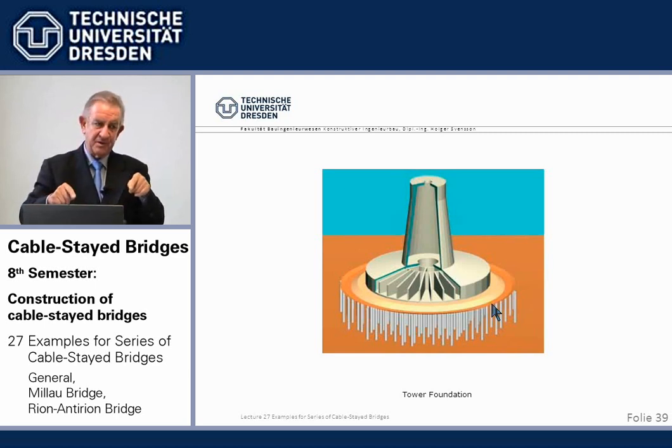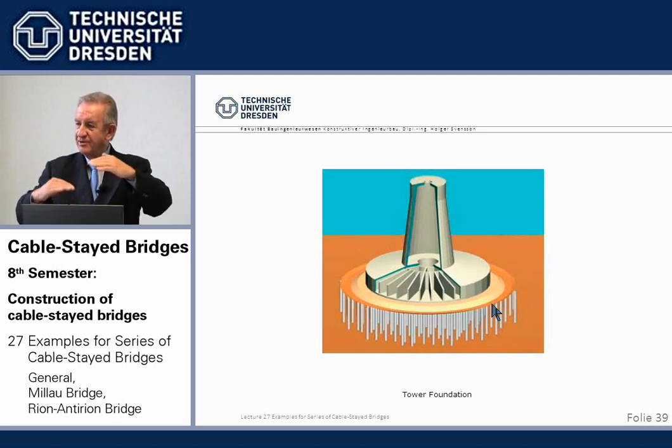It's not the first application at all. I've given you the reference, but it's the first for bridges. I think it has been done for buildings or so, but it's the first time. And it has been also used, you may recall the Golden Ears Bridge in Vancouver, BC, which I showed you. It's an extradosed bridge by Bilfinger, lately completed, where I was checking engineer. And they have also taken this because there's also the earthquake. Plastic movement within the gravel layer to take up the up to 2 meters.